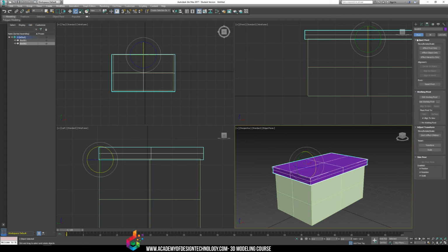And remember, anything inside 3D Studio Max that's blue means it's active. Anything that's gray means it's inactive at the moment. So don't forget to try and play around with not only standard primitives, but extended primitives and different things like doors and windows and stairs. We'll touch upon other objects later, but I think those will be fine for now. And don't forget to go into your modify panel, add edit poly, play around, and then go to your hierarchy and change the pivot points of where things are located, and you'll have an easier time animating objects and moving them around in your scenes.